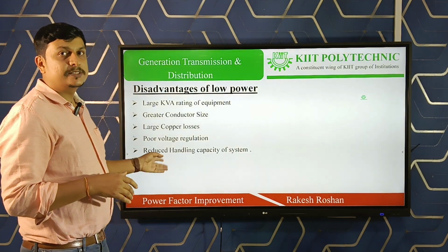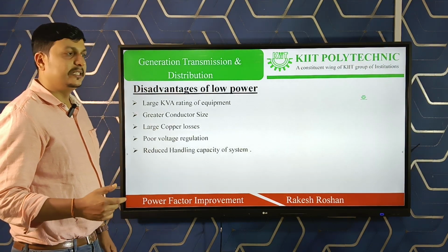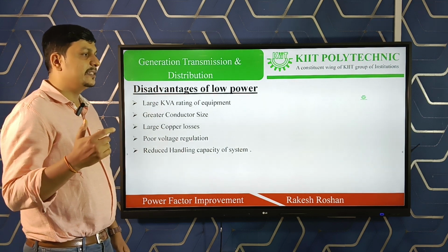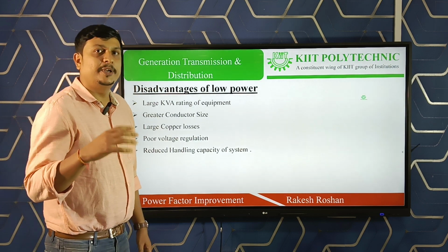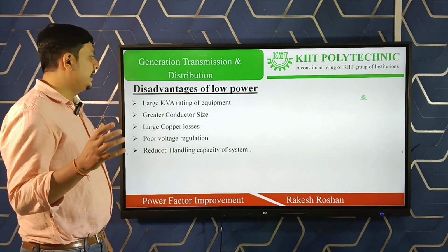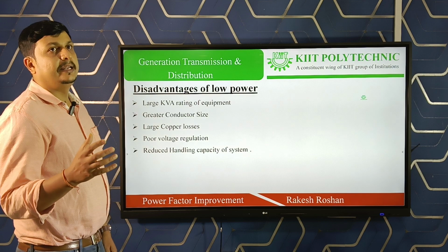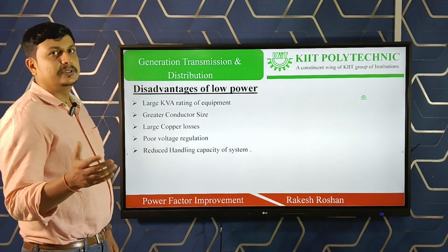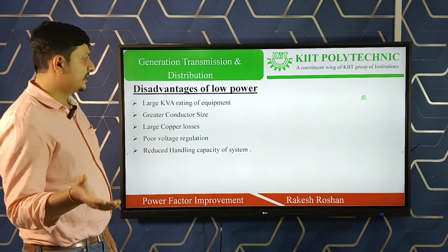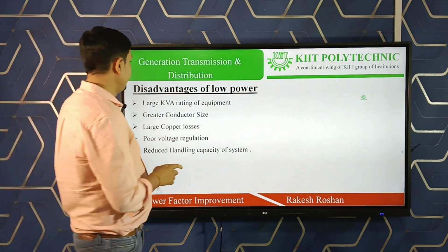And the next point, reduced handling capacity. Reduced handling capacity means there is more reactive power component for the same kVA rating. Reactive power in the system is more as compared to active power, so the overall handling capacity of the system is reduced.